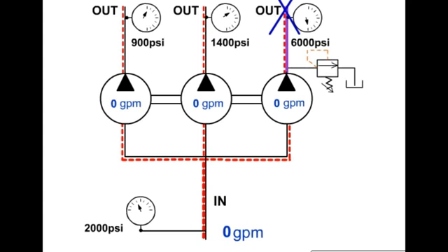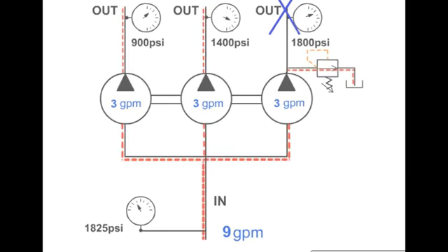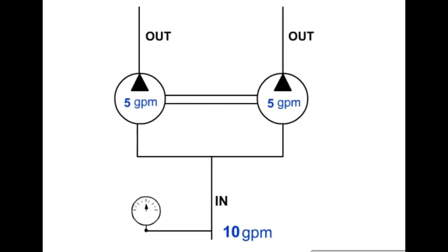A relief valve placed in the circuits downstream of a proportional flow divider will prevent pressure intensification. The relief valve will also keep the flow divider from blocking flow to other circuits. Gear-type flow dividers can be used to combine return flow in circuits. Most spool flow dividers are not designed to allow reverse flow through them. There are spool-type combiners and combination divider-combiner units.